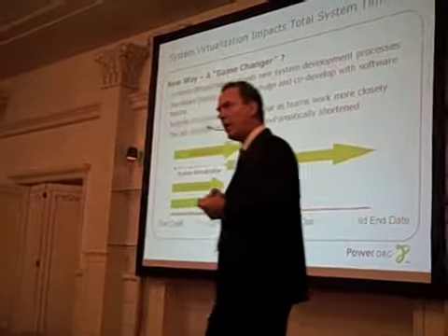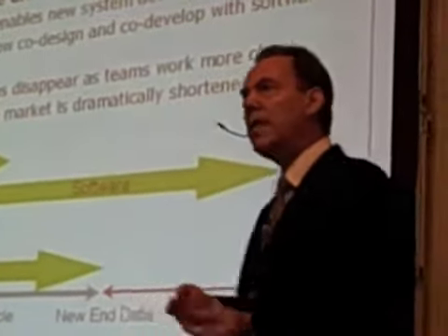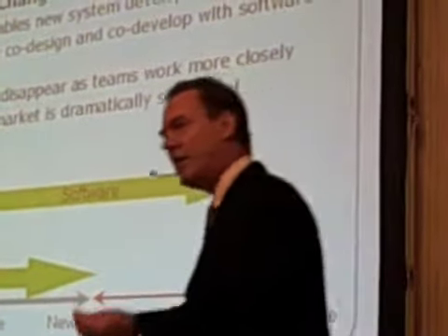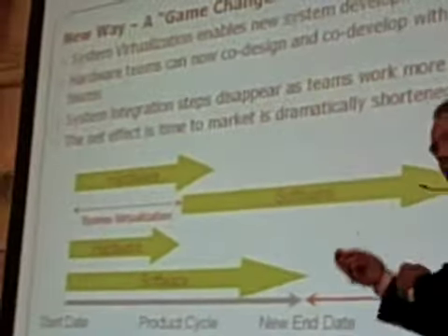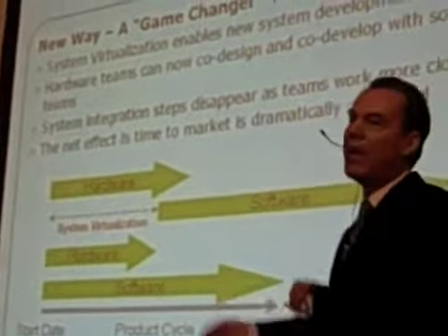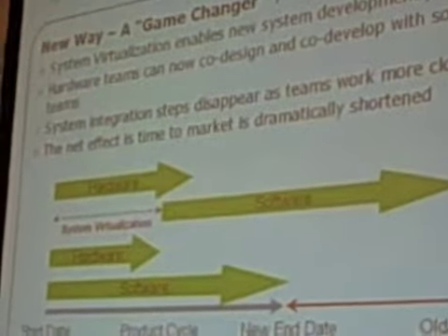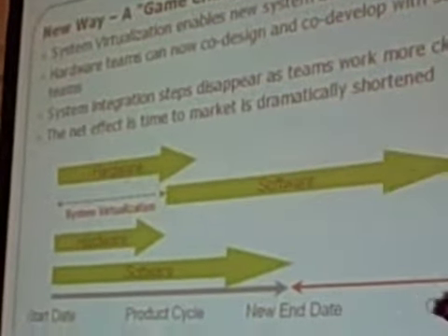If the hardware engineer is trying to decide whether to run this on 2-core, 4-core or 8-core, they can test that very simply in the model, because the model is very easy to change. So you get away from an over-design or an under-design at this very early stage, by being able to run the software stack early on, and that helps the hardware decisions.